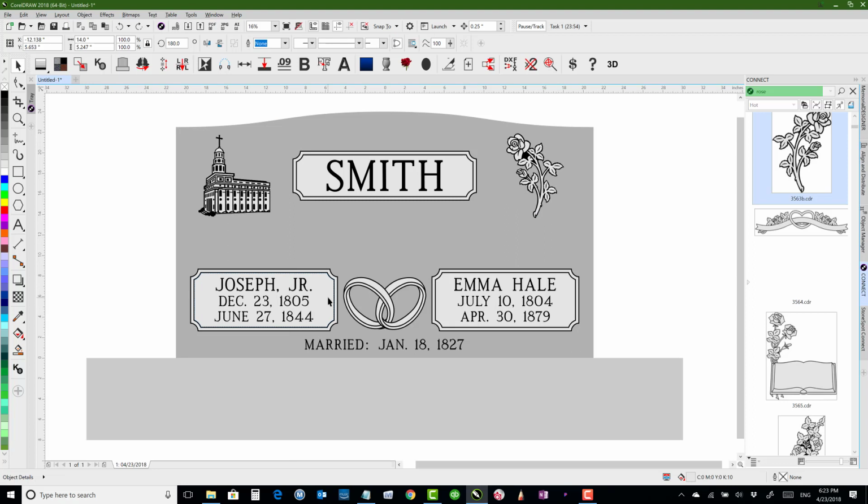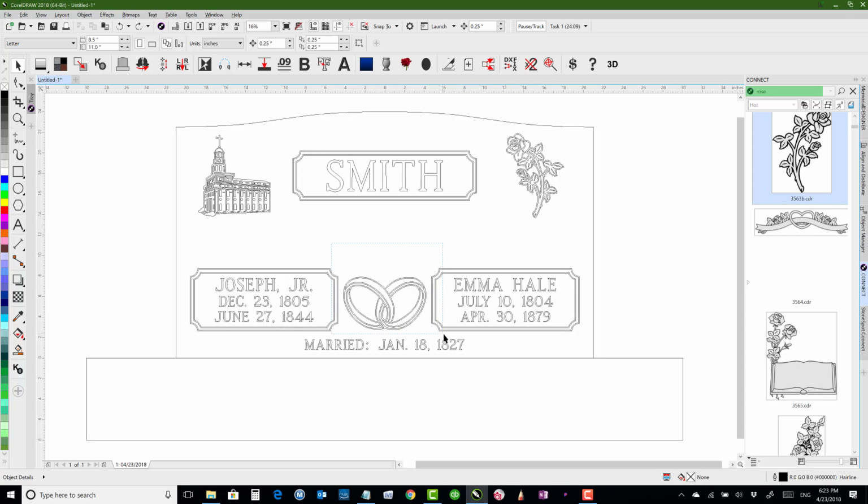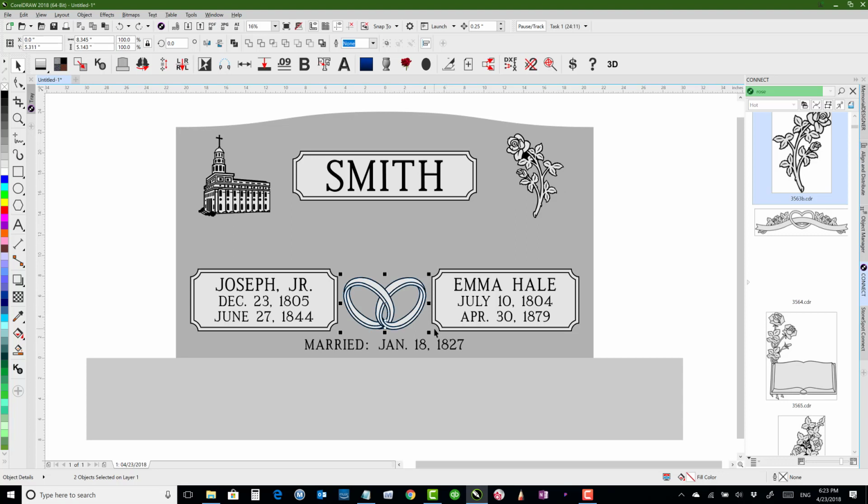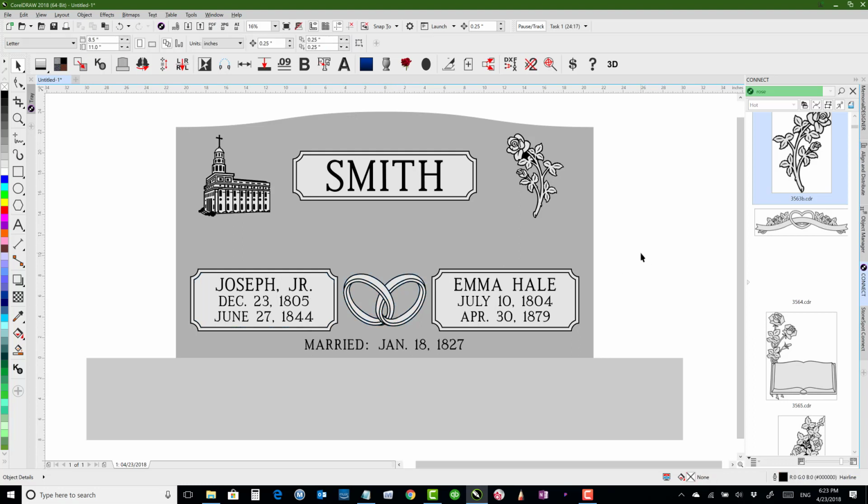Anything that's filled, when you click on it anywhere on that filled area, it ends up selecting it and moving it, so that's not what we want to do. So I'll hit V, click and drag, hit V again, and then shift select the panel and hit E, and that will then center it top to bottom. So that doesn't look too bad.